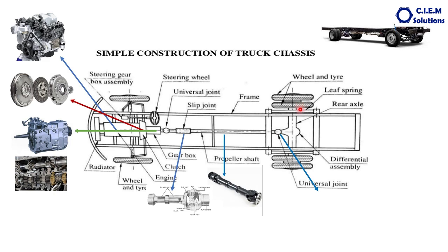So when the wheels are taking up and down movement because of the road conditions, the distance between these two points will vary, either shortens or lengthens. To accommodate that varying length, varying distance between these two center points, a slip joint is provided so that it can slide inside like this. One member can slide inside like this depending on the vary of the distance.